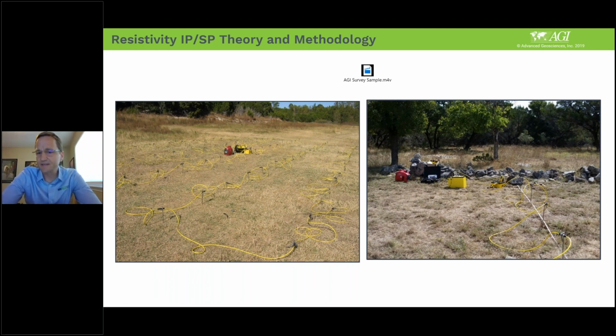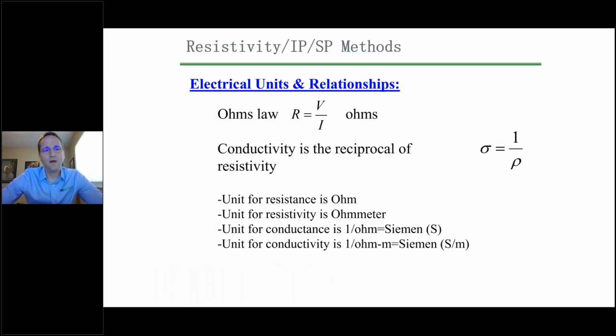So if you do have access to a small Honda generator, we have these generator power supplies that are two yellow boxes. You can just barely see them off to the right here. That would run the Super Sting, and that whole system doesn't need to be recharged. It's a lot easier to use, and it'll run 8 hours on the small internal gas tank there. So that'll give you that full 200 watts of power.